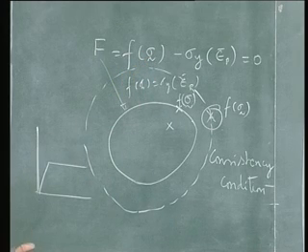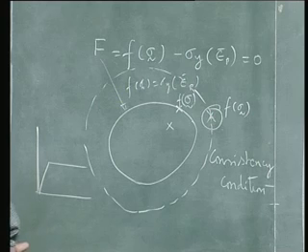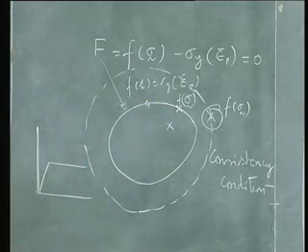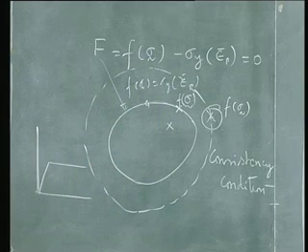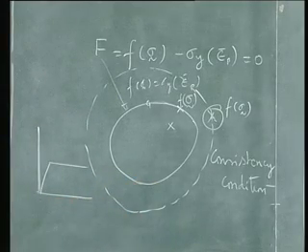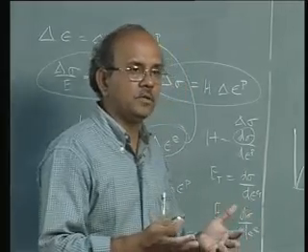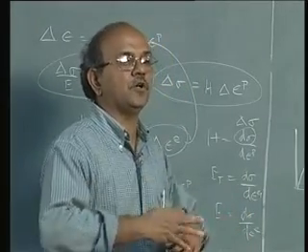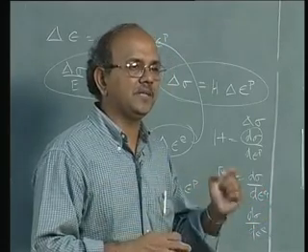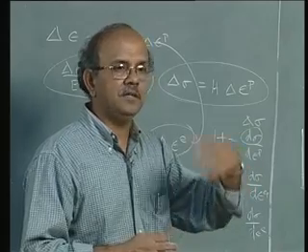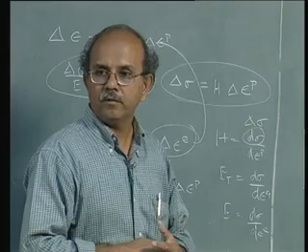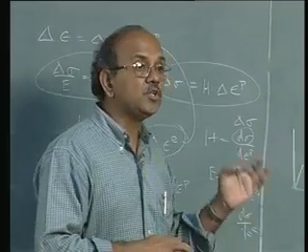So whatever you do to the loading actually makes the point move from one point to the other on the original yield surface. So in other words, even though I load it, okay, I can't move outside the yield surface, and the yield surface also will not dilate but will remain there, and what I will ultimately achieve is to move from one point on the stationary surface to another point on the stationary surface, right. So this is what is called neutral loading.